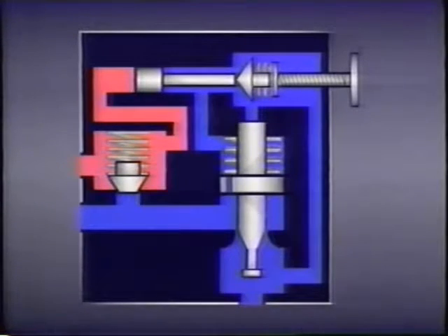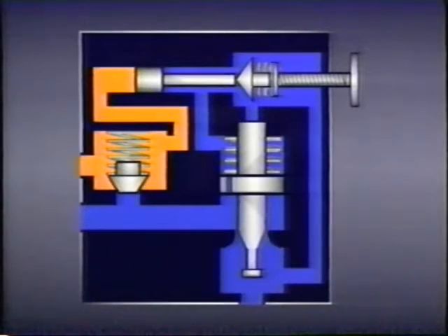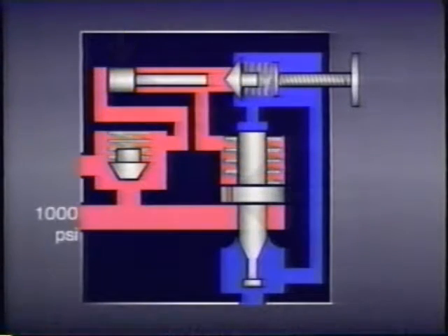When that happens, inlet pressure drops, and the check valve closes, preventing the accumulator from discharging through the relief valve to tank. However, when the accumulator discharges enough fluid into the system that its pressure drops to 850 psi, the pressure on one side of the differential piston also drops. When this happens, the piston shifts back. The tension of the spring reseats the dart, and pressure begins rising again as the accumulator fills with fluid.